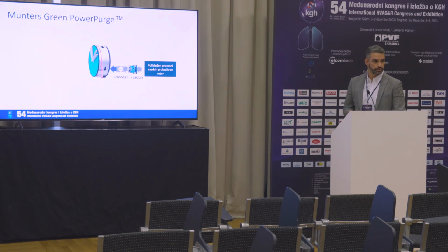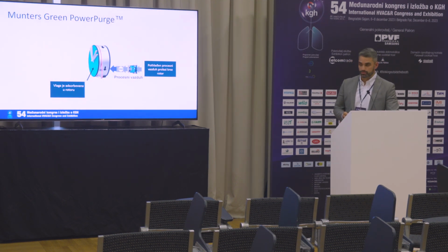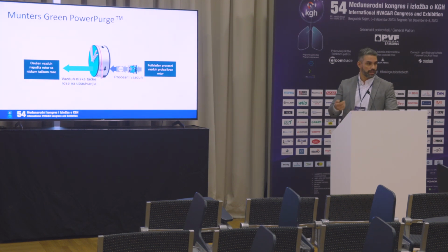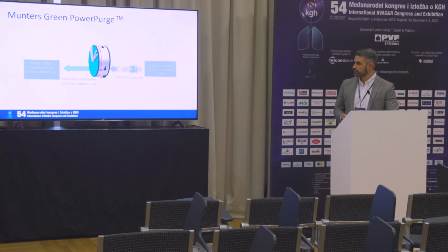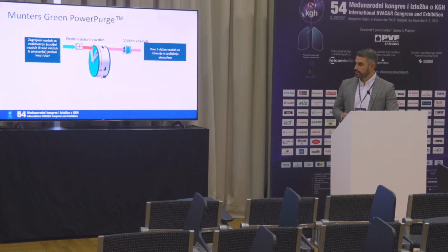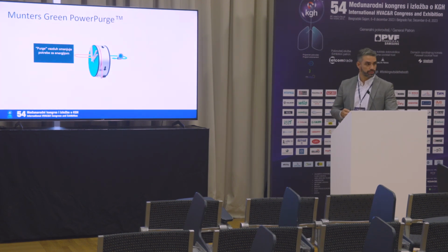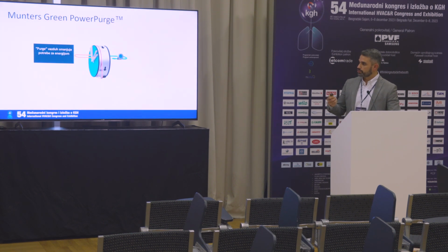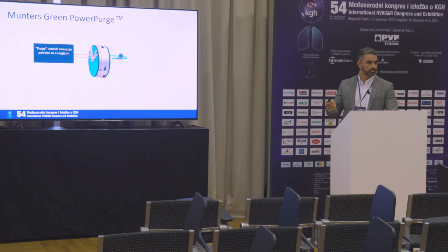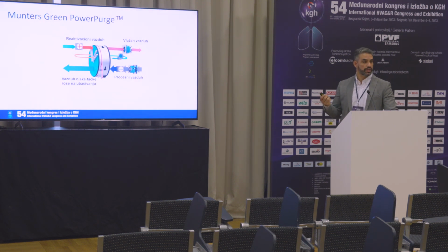So we have the process air, which is pre-cooled, going through HPX rotor with molecular sieve and supplied as air with low dew point. The reactivation part remains the same, but what is patented, what is heavily used is the power purge, which means that adsorption and desorption are happening continuously. In one run, you're basically removing the moisture from the rotor and reducing the temperature, while on the other side, you're helping the reactivation part by increasing the temperature for the load. And this is beneficial because you're not losing any process air in any process volume of the air.